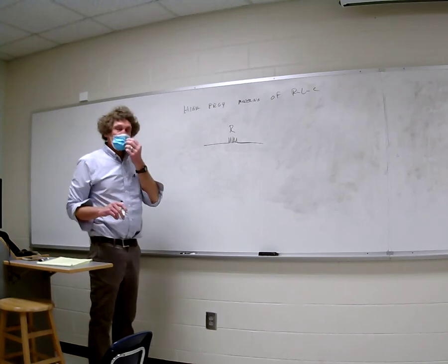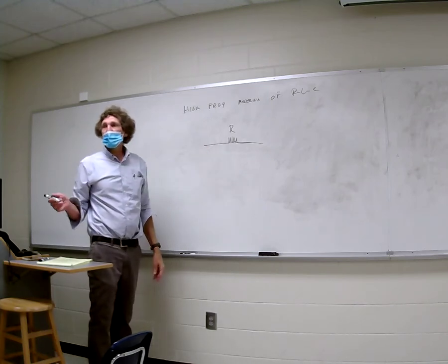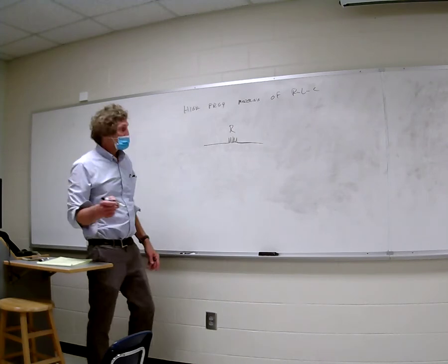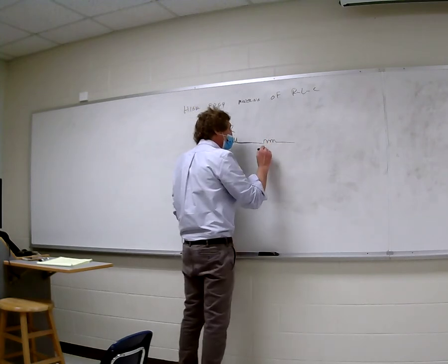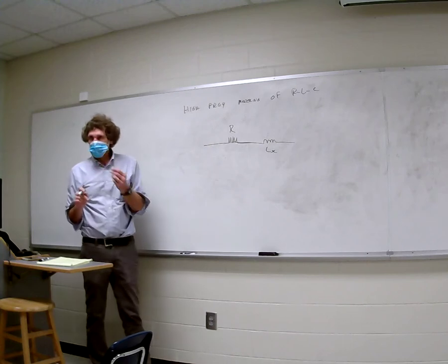Now, what does a resistor look like? Always think of what it's made of. It has to have wire. Whenever you think of wire, you think of inductance. That's the way it is. So normally when they model this, they'll put a little squiggly line here, and LX. I like to say unwanted inductance.